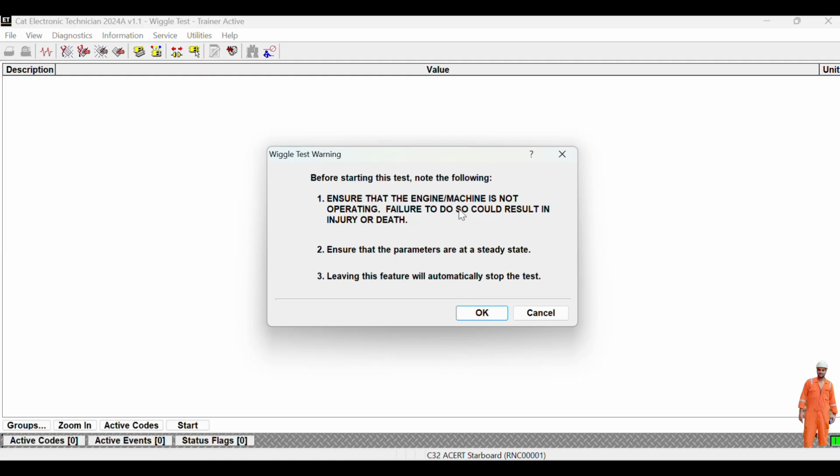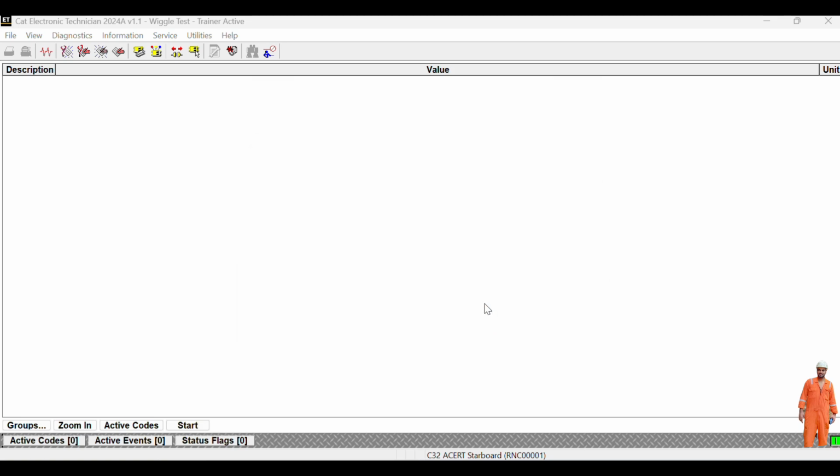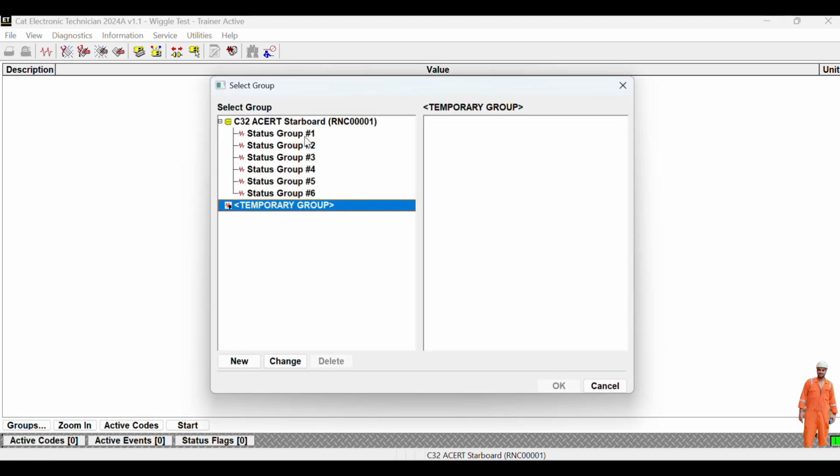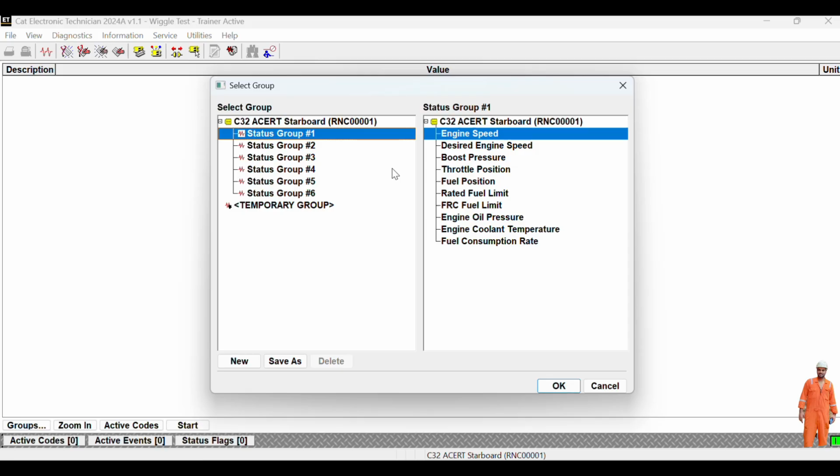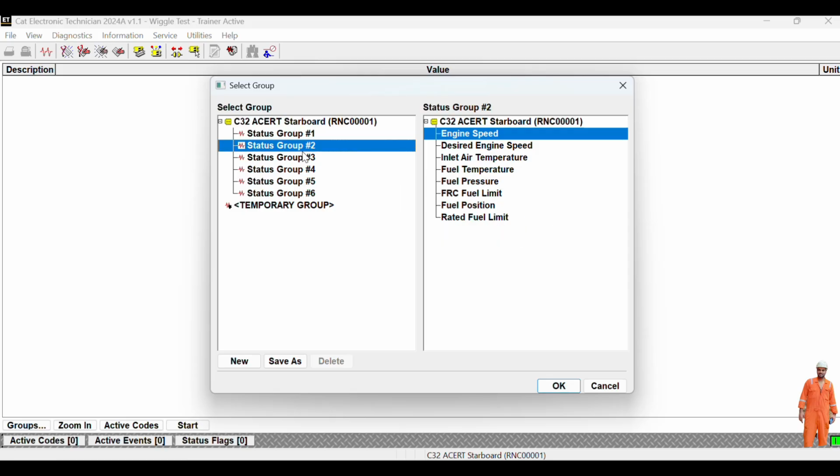Now I go back, diagnostic test. What is the next? Vehicle test. What is a vehicle test? Ensure that the engine is not operating. The vehicle test is carried out when engines are not operating, because wiggling tests are not modern, these are the very old technique of just wiggling and checking is there any loose contact or is there any change in the things that are happening. Like if I say I want to carry out a vehicle test, make sure that engines are stopped.